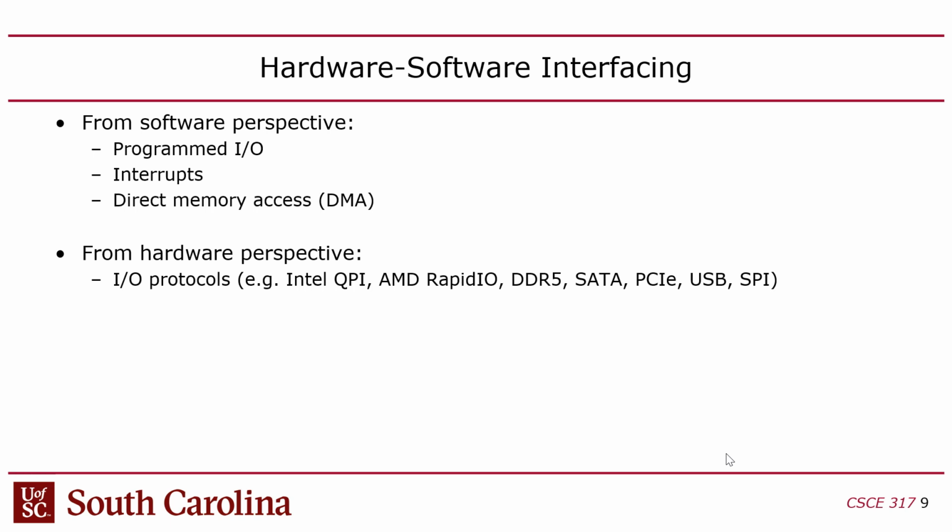Okay, so anyway, in this class, since we're focusing on cyber-physical systems, you will now have the opportunity to work without an operating system and do direct software-hardware interfacing. So if you ever have to write a driver, or if you're ever designing a system like this, you'll have that experience. Now, programmed I/O is a way for the CPU to act as a master and either send a value out to hardware, or explicitly read a number from hardware, right? But the CPU has to initiate that process.